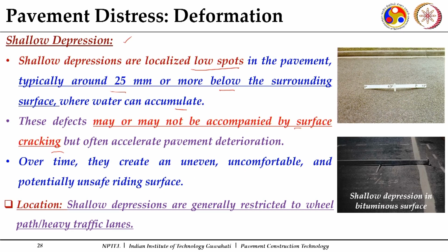If this depression is more, many a times you can see some cracks also getting initiated along with these shallow depressions. They may create an uneven, uncomfortable, potentially unsafe driving, because the water can pond in these shallow depressions. Shallow depressions are generally restricted to the wheel path, heavy traffic lanes, where you can see this is an edge marking, this is a shallow depression which is happening.